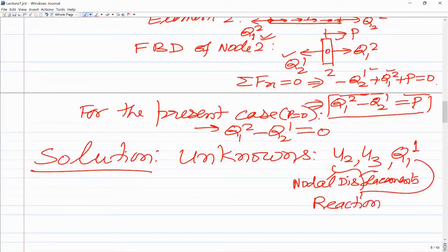You may say that we are trying to solve the whole problem through finite element, so we are not bringing in equilibrium. Although this is statically determinate, so you can get the reaction at the left end for the whole rod if you draw the free body diagram of the whole rod and apply sum of forces along the x direction equal to 0.